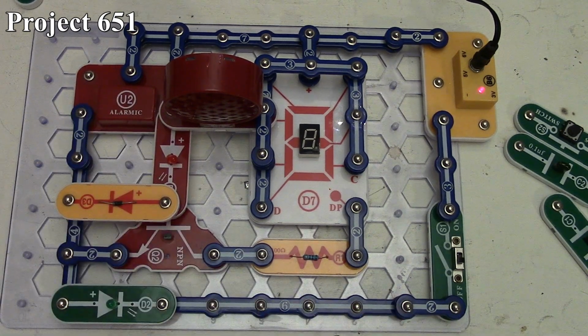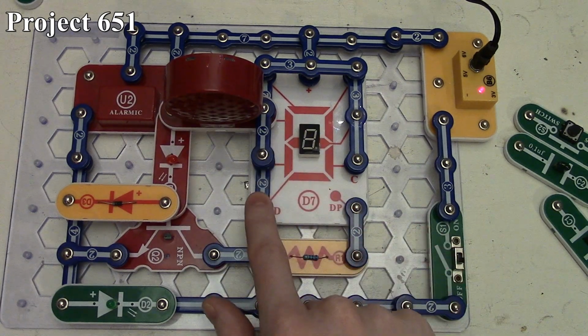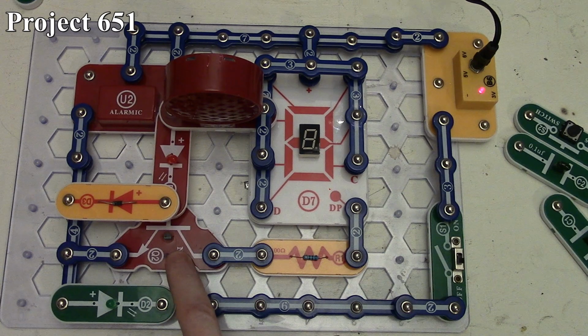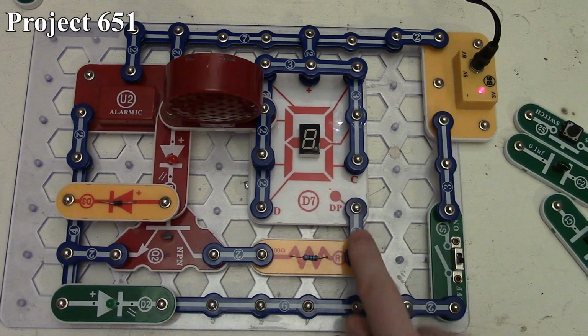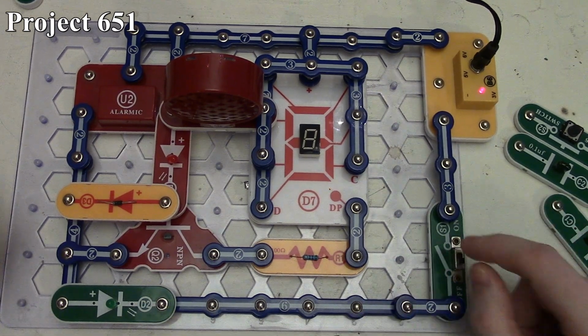We're using our alarm IC, which is being outputted to both our speaker, and then it also runs down through our red LED into the base of our NPN transistor, which is also being offset by our regular D3 diode. And the decimal point is connected to our 100 ohm resistor through the collector of our NPN transistor. So that's what's being controlled there. And then everything is, of course, being dropped across our green D2 LED at the bottom.